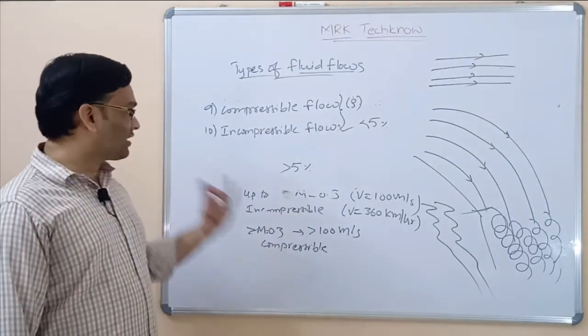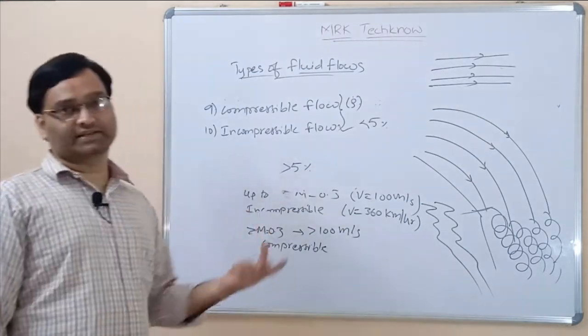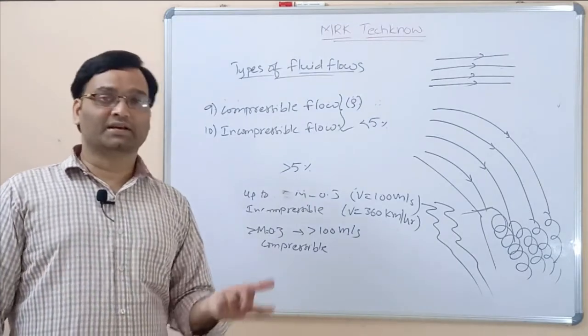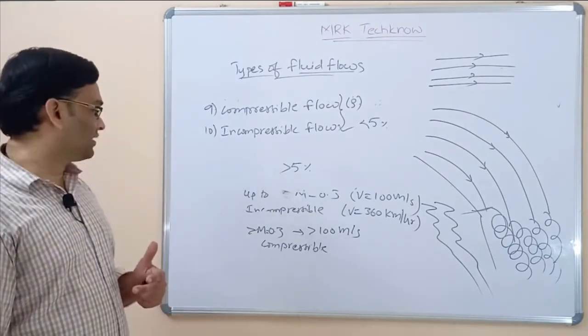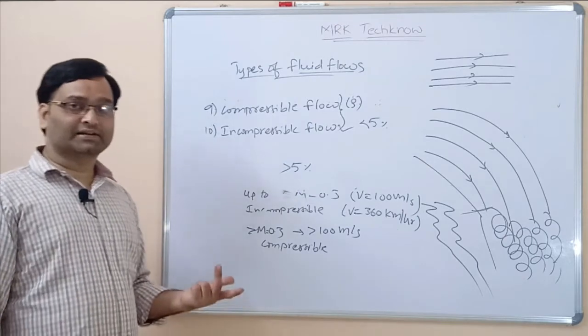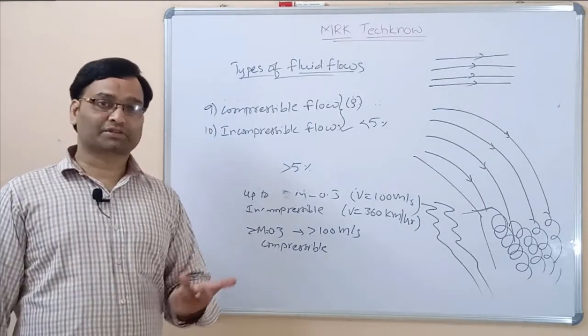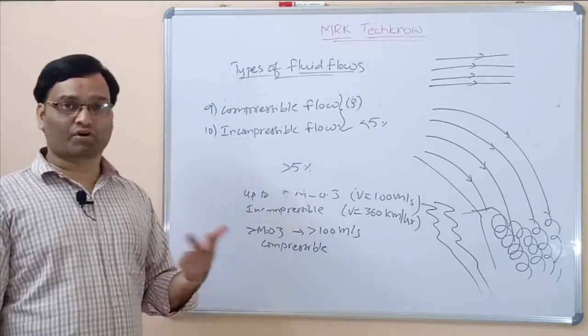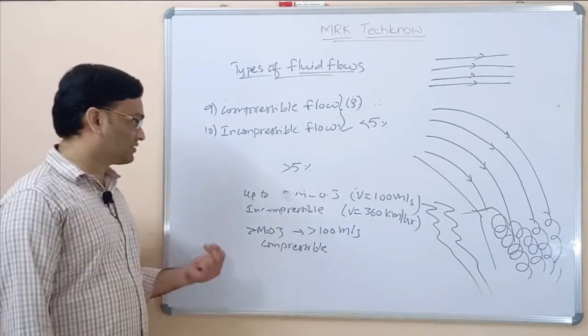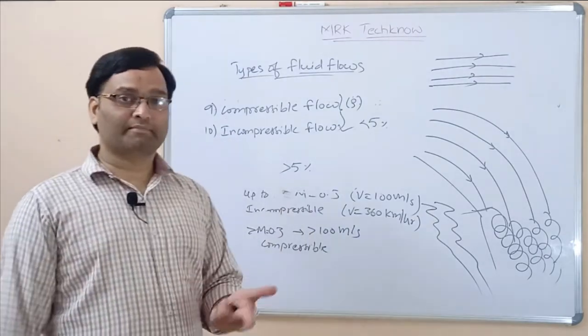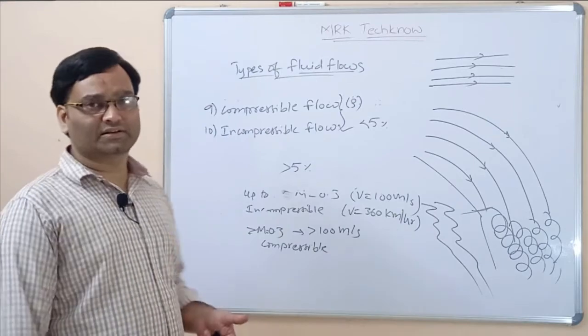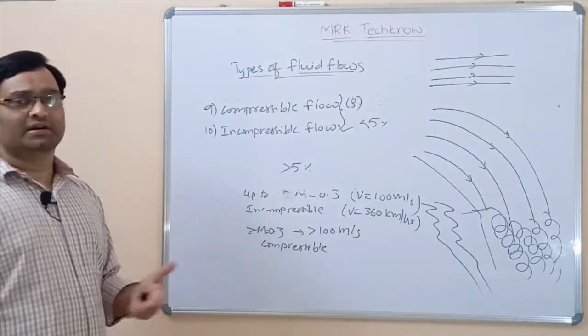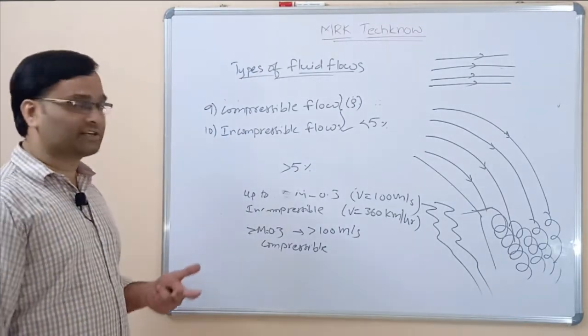Okay, and the first case is a low speed subsonic wind tunnel. In the second case, if you have a supersonic wind tunnel, then you can make calculations taking atmospheric vehicles like aircraft, rockets, and beyond-atmospheric vehicles also, which travel more than Mach 2. So you can use the supersonic wind tunnel estimations, and you can further do the experiments and generate the results.